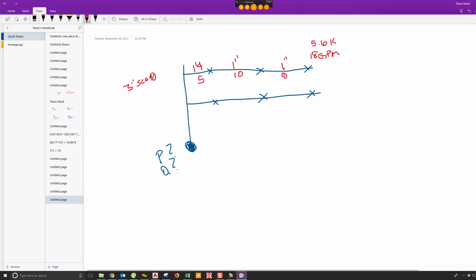So we're going to have to figure out what the flows and stuff is here. This is where we're going to start throwing in fittings. We're going to learn how to choose the fittings that we do. And we're going to learn the concept of an equivalent K factor. So let's say that this is 12 feet here. 12 feet, and then we'll just say that this is 6 feet just because it's halfway through or something.